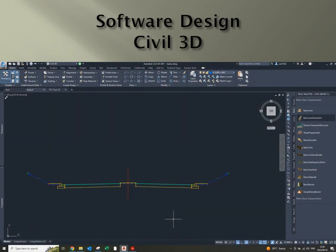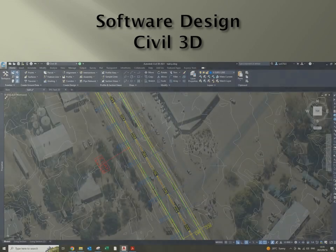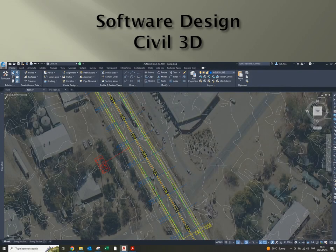From here I have created an assembly. I have created a corridor from the assembly. A few steps later we come close to the final product. Here is the road with contour lines. I have added the intersections with the intersection tool of Civil 3D and added them on the exact intersection places.